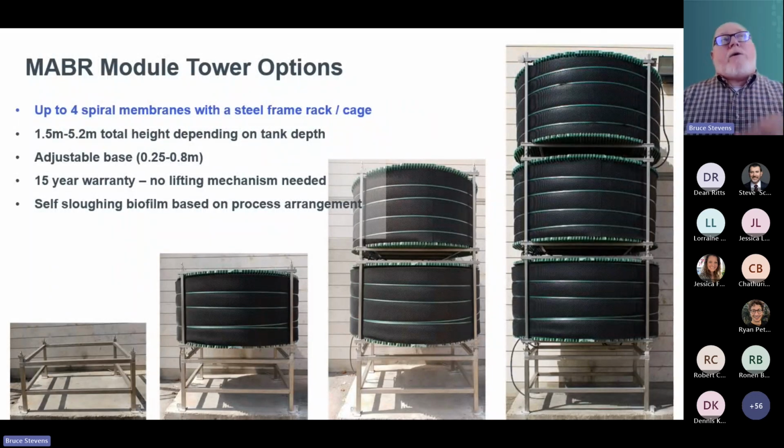So the DO is not non-existent in that tank. It's still an anoxic tank. That coarse bubble airlift just happens, like I said, every 30 minutes or so, and it circulates the whole tank quickly, gives it turnover, and gives food to the biofilm. There's a natural sloughing of the biofilm. We don't have a scouring system of any sort to keep it clean. We haven't experienced excess growth or run into problems of any kind. That's just our mechanism, our technique.